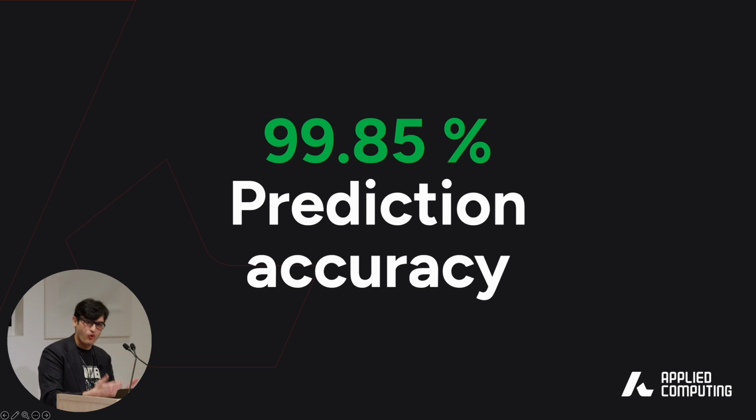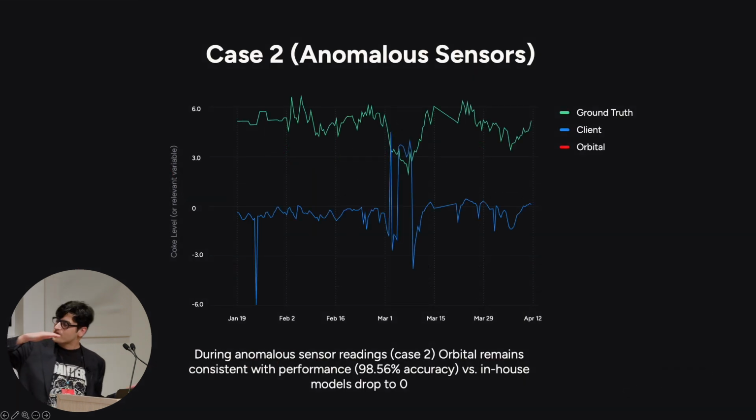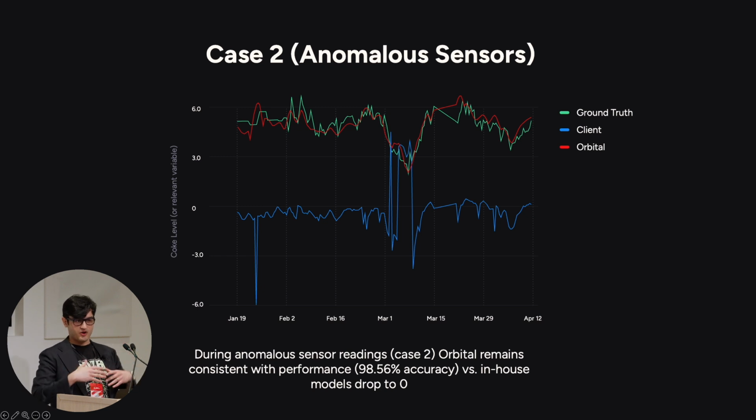They weren't reporting the right results, which is very typical in a refinery, where sensors, to some degree, lie because their numbers also shift. And what had happened was their models, during this anomalous sensor period, weren't able to predict coke buildup. In that case, they just bottomed out at 0 because it wasn't trained for that distribution. So as soon as sensor results were out of the norm, the model fails, right? Which is expected because it's out of the normal distribution. This is typically known as drift.